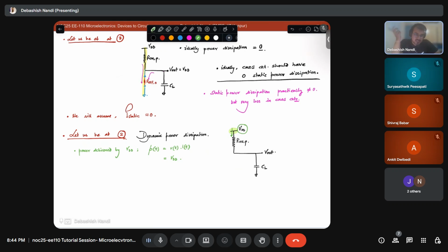So see, you have to understand your basic RC circuits very clearly. Who controls the current in this case? This is a series combination, right? So the same current has to flow through the entire circuit. And what is the controlling element of the current here? This is your capacitance, right? That controls the dynamics of the current. So this will be C dV out by dt, right? Yes, sir.